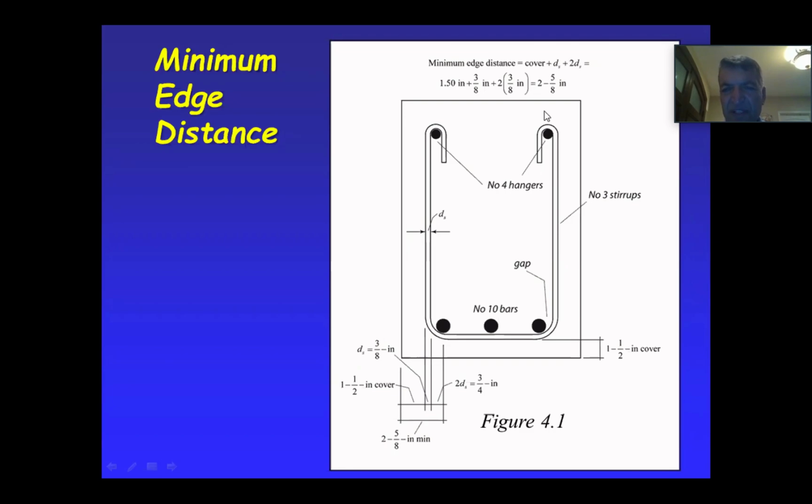And look at this, number 3 stirrups. One reason we use that is for the shear reinforcement. Second, what if you have 2 top bars, and we will see that. Sometimes you have to put bars at the top. How are you going to hold those? These are going to hold them. We call them hangers. So you're going to put this and then tie this bar with that with a fine wire. Okay. And then here all the diameters and all that stuff. We're not going to go into a lot of details like that, but please, for the first time, just study that, and you will see when we start designing, you'll be able to do it.